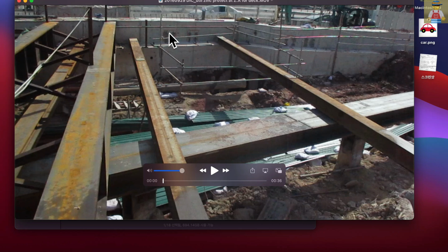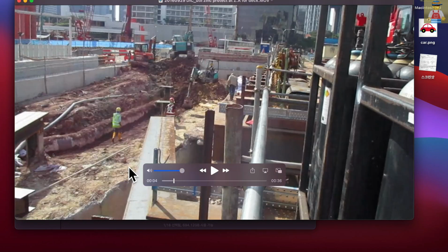And the secondary beam will be installed here one more. Then you can see that below, the utility will be supported down by angle from this beam. So during the installation time, to prevent any mechanical hit from damage, we protect with zinc sheet, a kind of steel plate, and continue to support the utilities. While we are supporting that, in another phase we excavate, exposing the 900 water pipe and other utilities to support later every 2 meter.